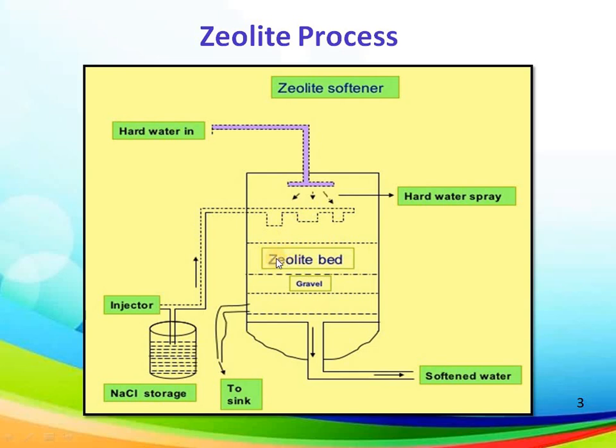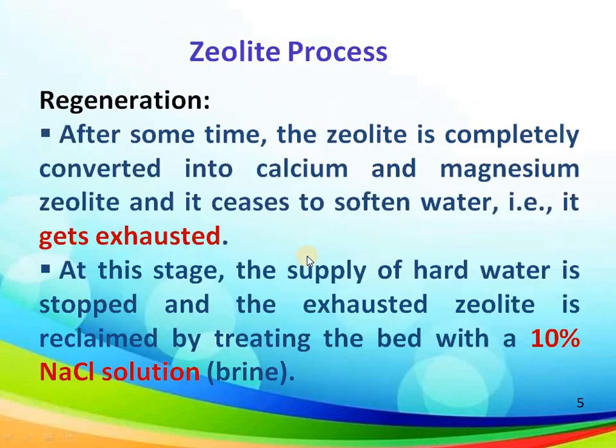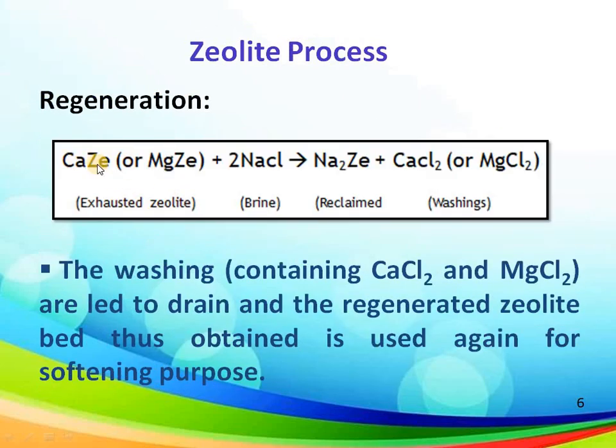Now NaCl reacts with calcium zeolite and magnesium zeolite, and it is again formed into sodium zeolite, meaning it is reclaimed and regenerated.